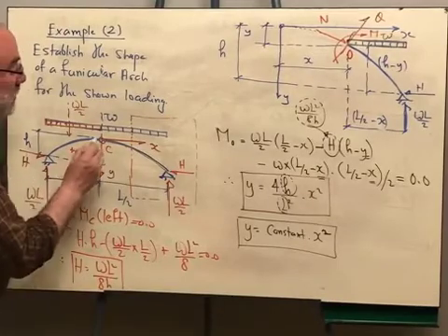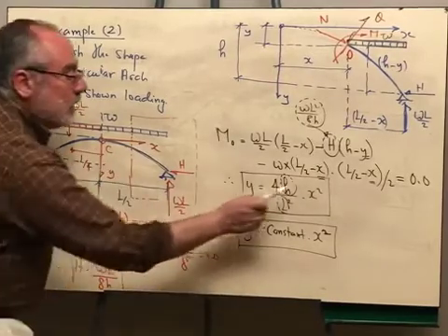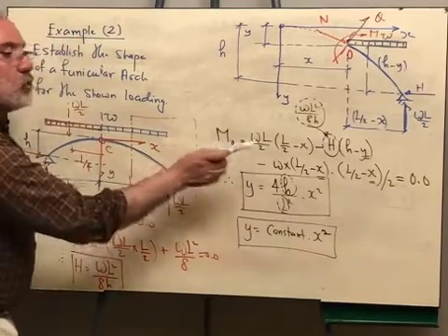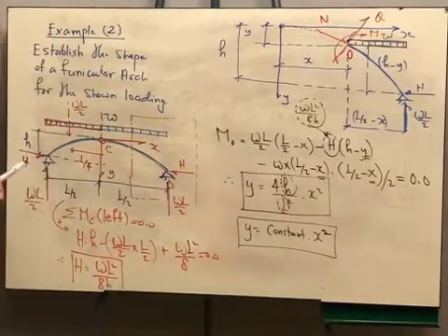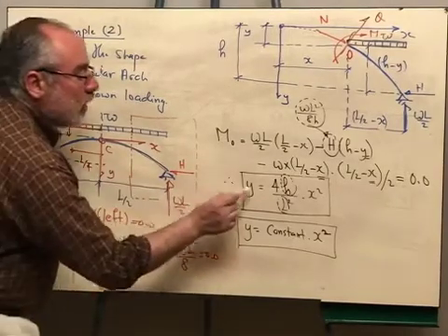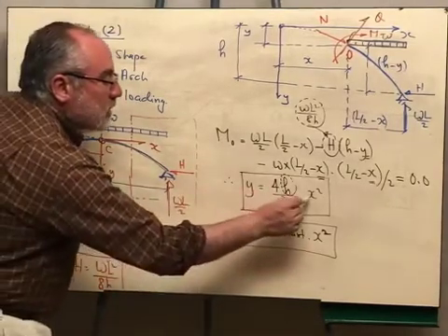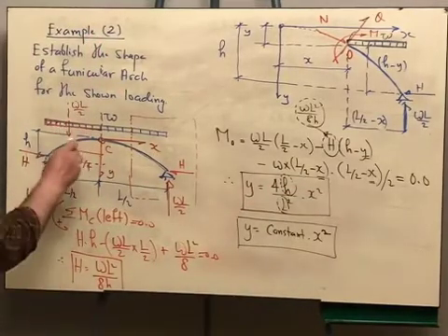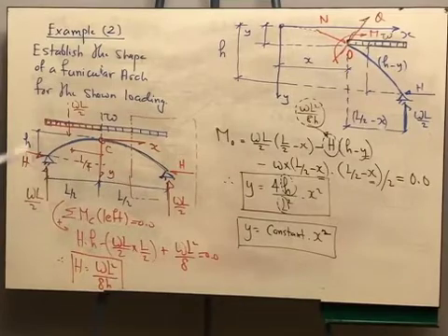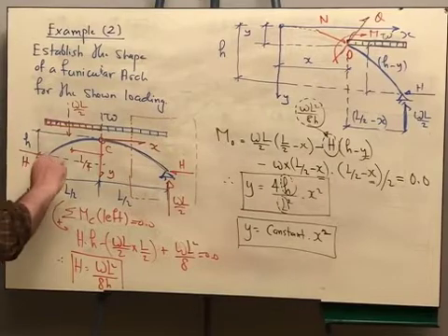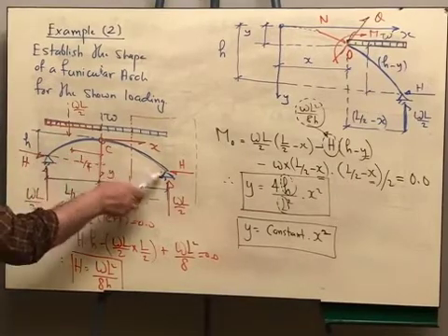Okay, if this is cubic, meaning instead of x square you made x cube, the moment M naught will no longer be equal to 0. Okay? And if this is straight, this means that y is equal to some constant multiplied by x to the power of 1, linear. So again this is no longer funicular and you will have internal bending moment. So the only case that this would be a funicular arch is a parabolic arch.